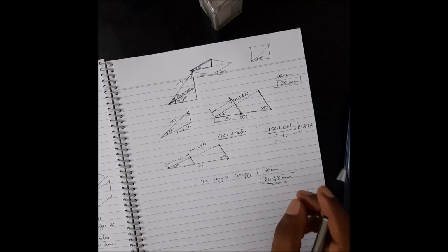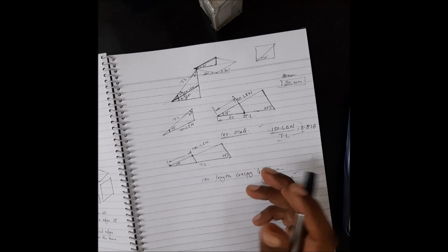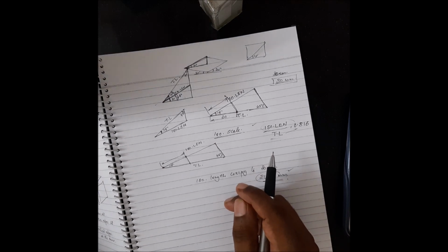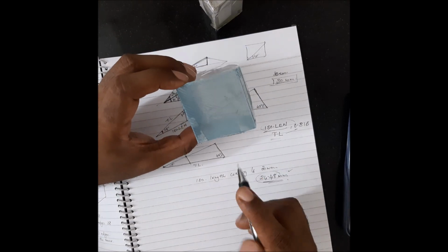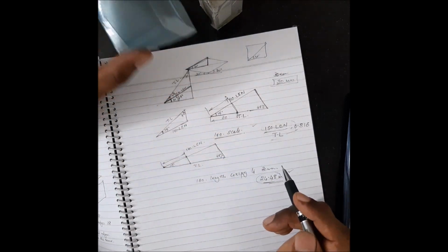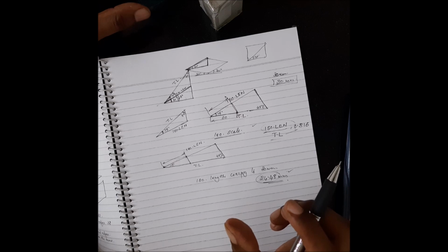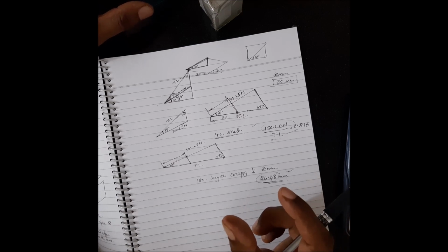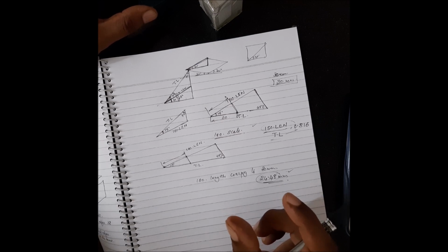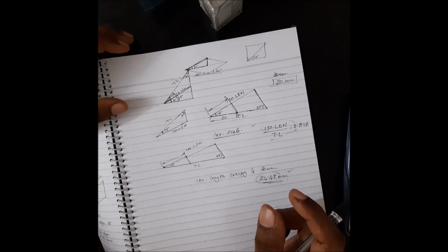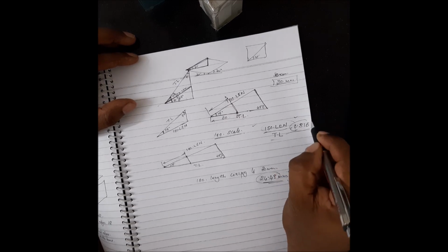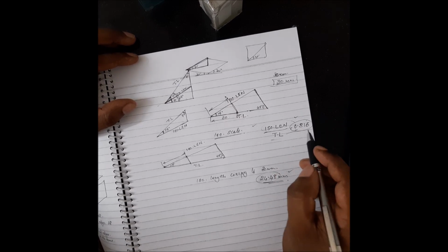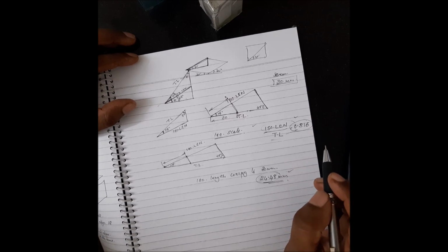So coming back to our question, how much foreshortening happens? When you keep the cube like this, all these edges are equally foreshortened, and how much shortening happens, that was our intention to find out. Now this is what we have found out. The length actually shortens by a factor of 0.816.